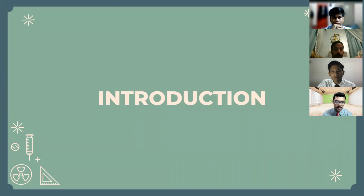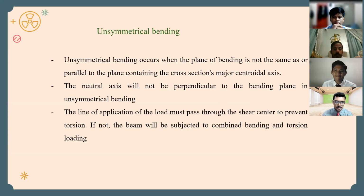Okay, thank you, boss. So for the introduction, this problem is related to asymmetrical bending. Asymmetrical bending occurs when the plane of bending is not the same as or parallel to the plane containing the cross-section's principal axis. The neutral axis will not be perpendicular to the bending plane in asymmetrical bending. The line of application of the load must pass through the shear center to prevent torsion. If not, the beam will be subjected to combined bending and torsion loading.